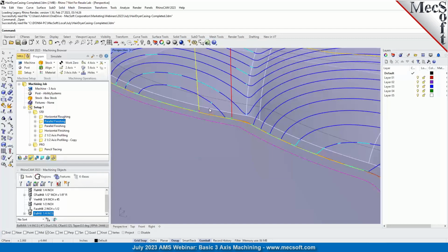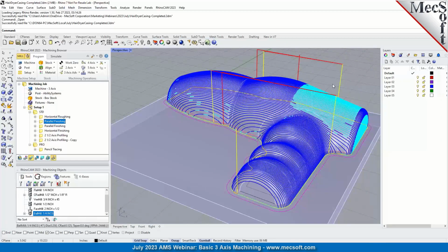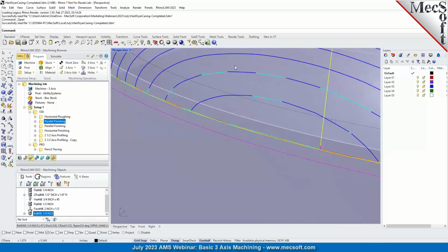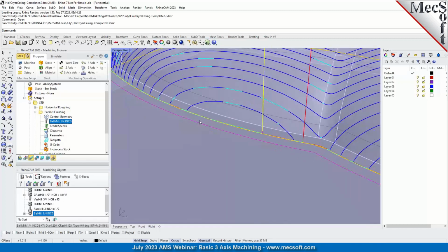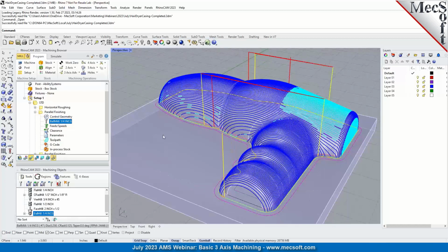Typically, when you're doing finishing and you want to contain it, offset your perimeter curve by 1/2 the tool diameter, which is basically the tool radius, and maybe a little bit more than that, in order to contain that tool path to that area. So we're coming all the way down, and you'll see that the tool, which is a 1/4 inch ball mill, is going to leave a 1/8 inch radius wherever it cuts. So that's the first approach at cutting that radius.